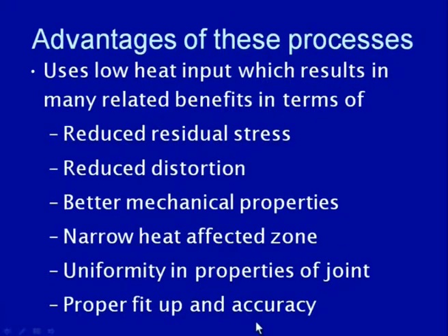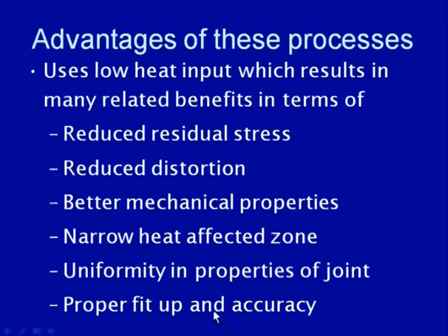In this case, the proper fit up and accuracy is also found to be better because of the lower heat input. With less heat input, no major dimensional change takes place in the base material during this process, and this in turn helps in having better accuracy and better fit up conditions during braze welding.